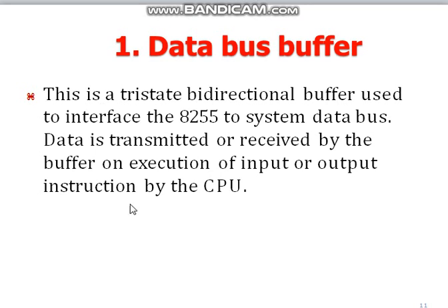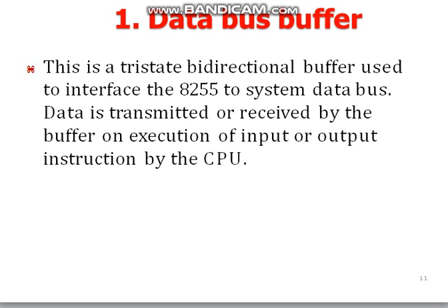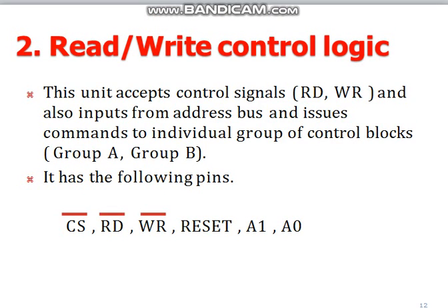Yes, the definition of all the components is put over here. The data bus buffer is used to store the data and transmit the data. The read-write control logic is the control circuit which controls your 8255. It consists of all the control parameters like chip select, read operation, write operation, reset, A1, A0, everything put together in this read-write control logic.